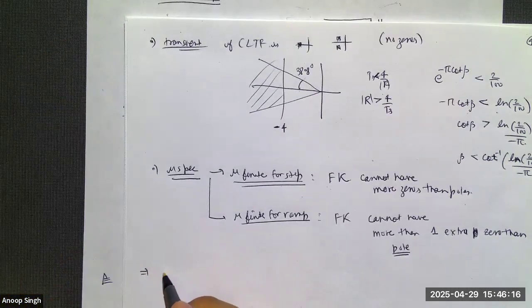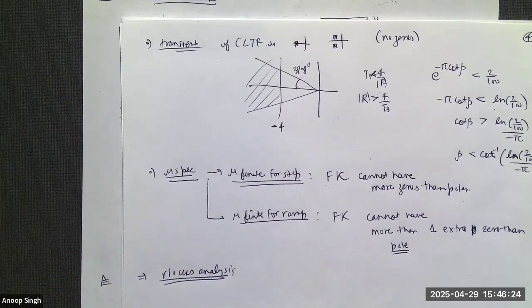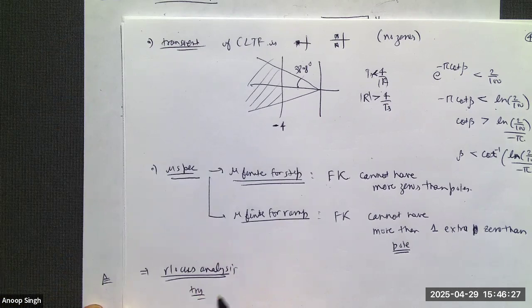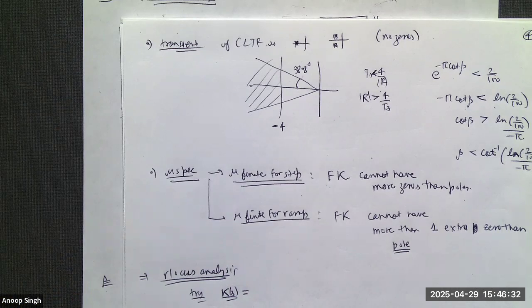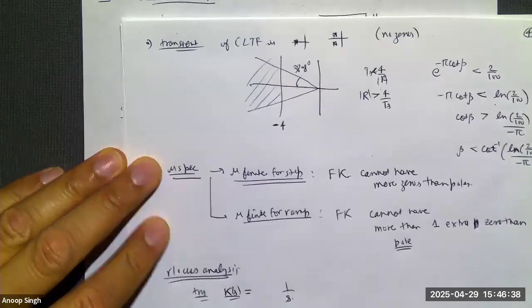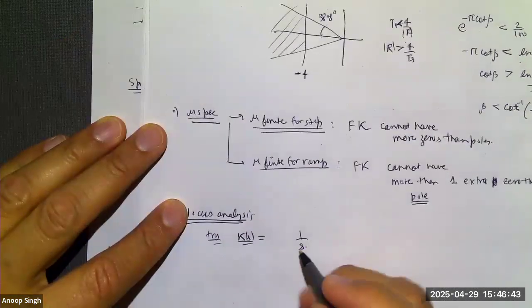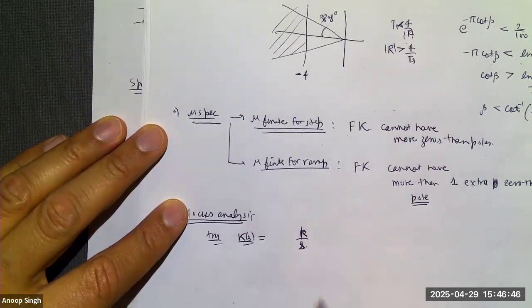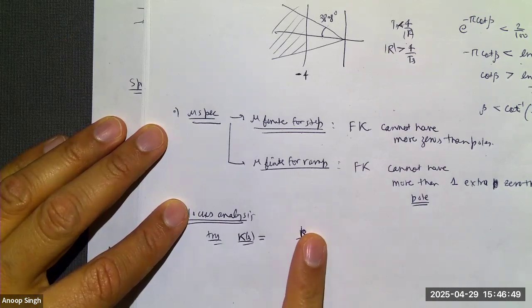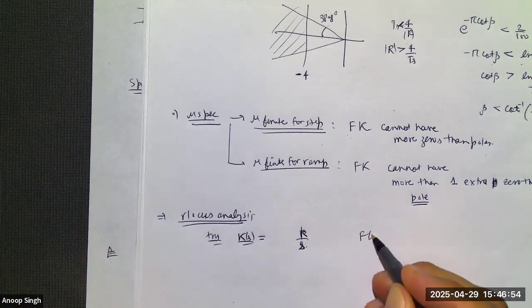So here is my first question for you. I'm about to do the root locus analysis. The whole purpose of root locus analysis is to see what kind of controller would actually get the job done. So I should try the simplest controller I can. So I need 1 over S in the controller, because of that error requirement. I'm going to try a controller which has some gain, because the root locus job is to change the gain of the controller and show me how the closed loop poles will move around. I'll try a controller with an integrator. What kind of pre-filter should I try?